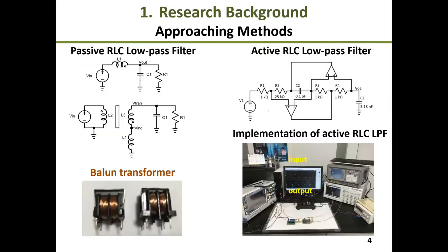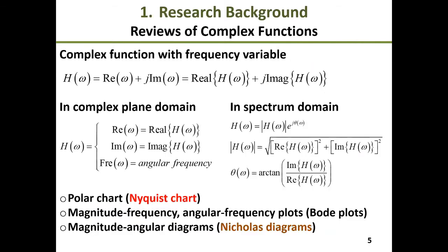First, we will analyze the typical second order passive RLC Butterworth filter, and then we will replace the passive inductor by an active one. We use a general impedance converter to design an active RLC Butterworth filter, and we verify the analysis by the practical measurement.